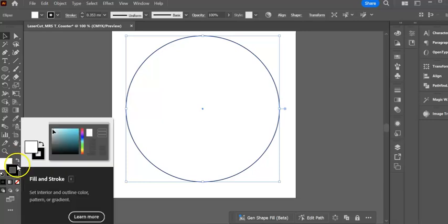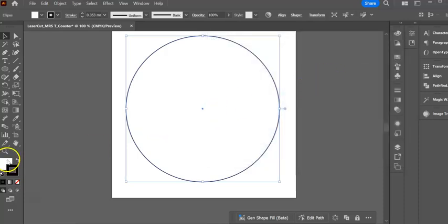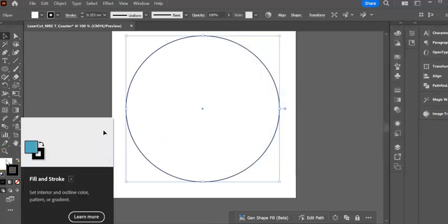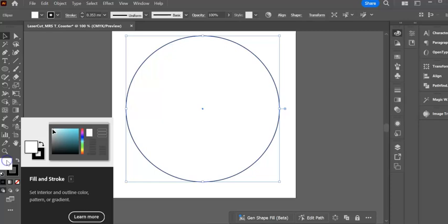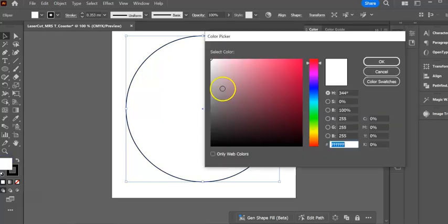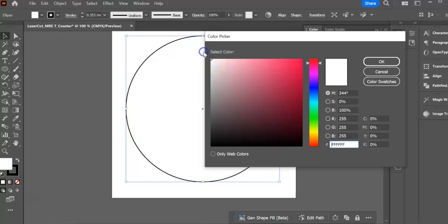Okay, and I just need to make sure that it is the right color so that when I take it to the laser cutter, it will actually read that. So just so you know what I'm doing here, I'm first of all going to get rid of the inside. Even though it's white on white, if I click on this shape here and double click it, you can see that it does have a fill inside of it.